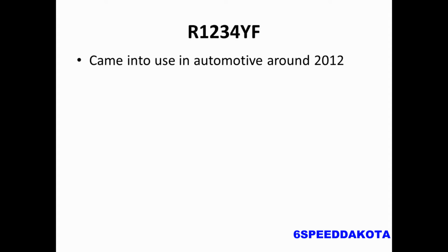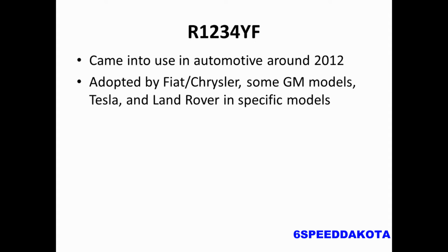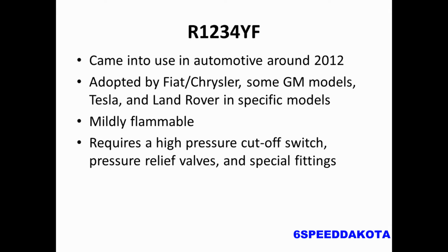So our R1234YF is a horse of a slightly different color here. It was approved for automotive use around 2012, and around 2014, I think, is when a few of them started appearing. It's been adopted by Fiat Chrysler, some GM models, a lot of Cadillac, Tesla and Land Rover in certain models. It is mildly flammable, unlike R12 and 134A. And this actually requires a high-pressure cutoff switch, a pressure relief valve, and special fittings so that you cannot charge it with the wrong stuff, and if there's an issue, it can vent.